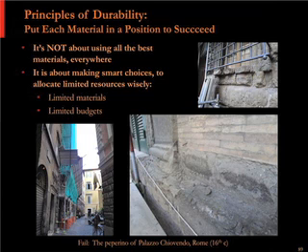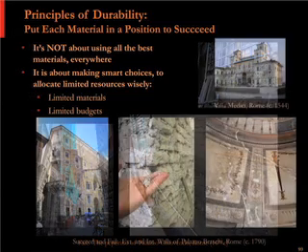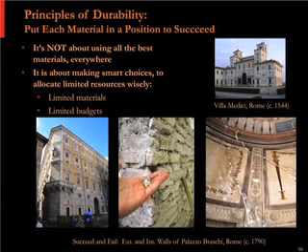This is a Renaissance palazzo where they took a stone that the Romans knew was not very durable. Typically they only used it as kind of a backup with other facing or in an unexposed area, and that's peperino. So it's a very dark stone, very dark color. Maybe they wanted that color on this building. But in the two photos at the right, you can see how badly it's falling apart. So it's kind of like their equivalent of our brownstone. Doesn't hold up that well to the weather.